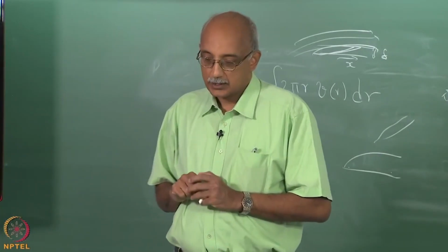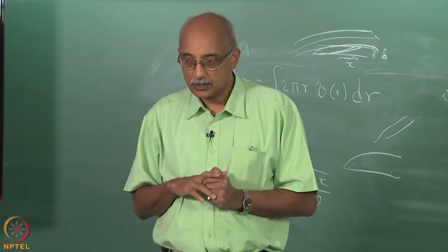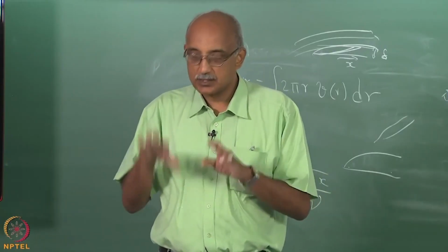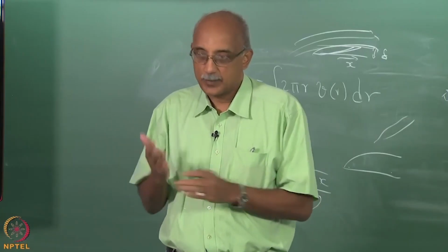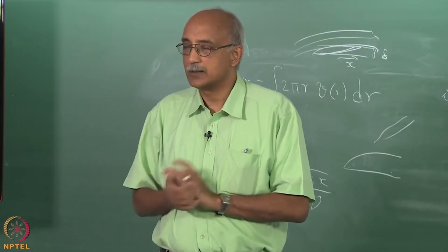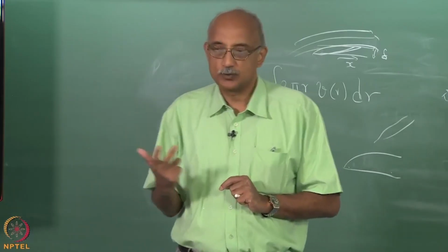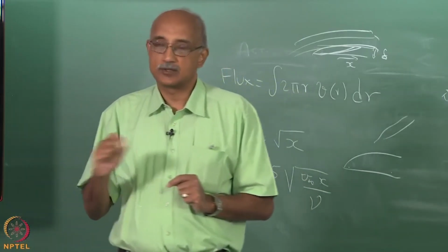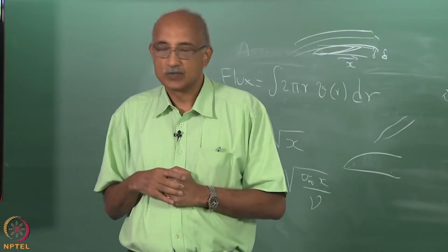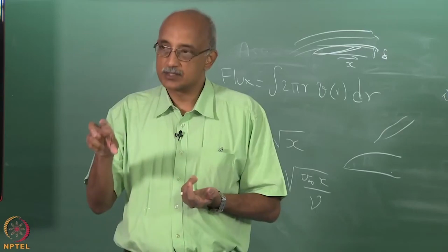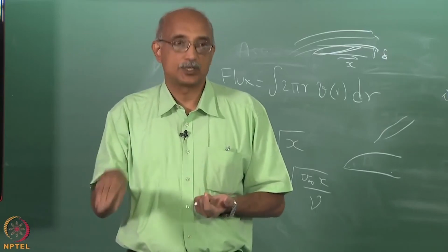The other aspect that again we will deal with in much more detail later on is this self consistency aspect. Let us say that you are trying to deposit silicon on a substrate. From a transport viewpoint, what is the primary constraint you have to impose on the system to get a meaningful solution? The constraint is the flux of silicon must be positive towards the substrate.